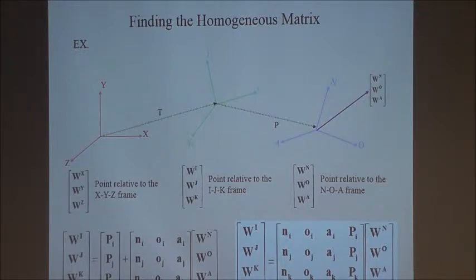Okay. As you might expect, it will consist of 1, 2, and 3 homogeneous transformation matrices. The red by itself has its own initial transformation matrix. In order to go to the green, it has to be post-multiplied by another 4 by 4 matrix to get there. And then at that point, you are at the green, you want to go to the blue, another one, 4 by 4 matrices.